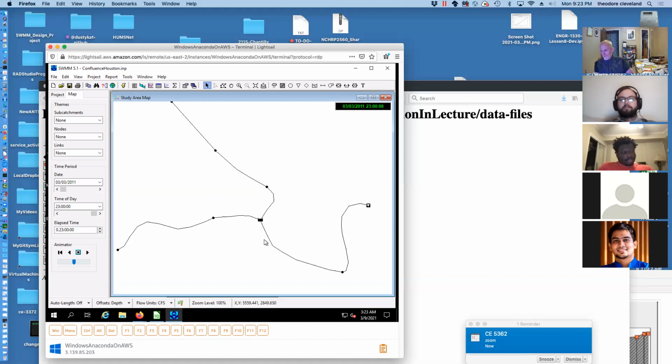So in review, before I call it a night, I think what we've done, we started with a single rectangular channel in steady flow. We added the necessary computational capability to handle unsteady flow. We changed the geometry from a rectangle to, in this case, any geometry that we can conceivably represent in tabular form.